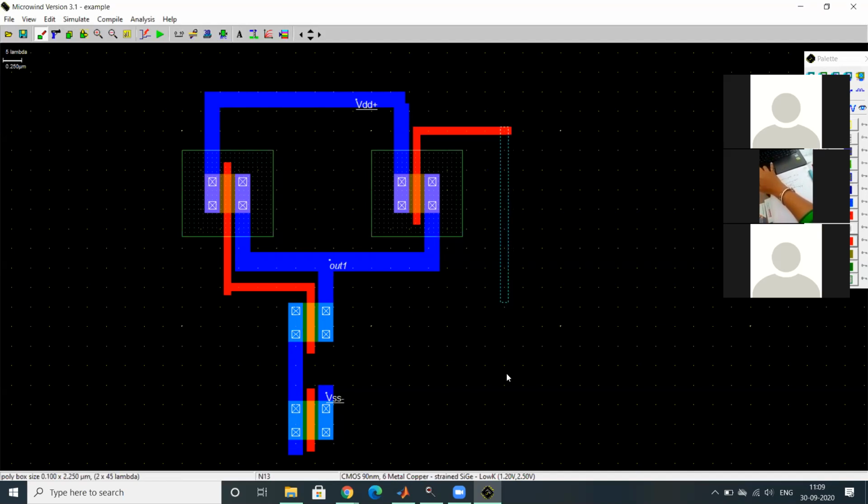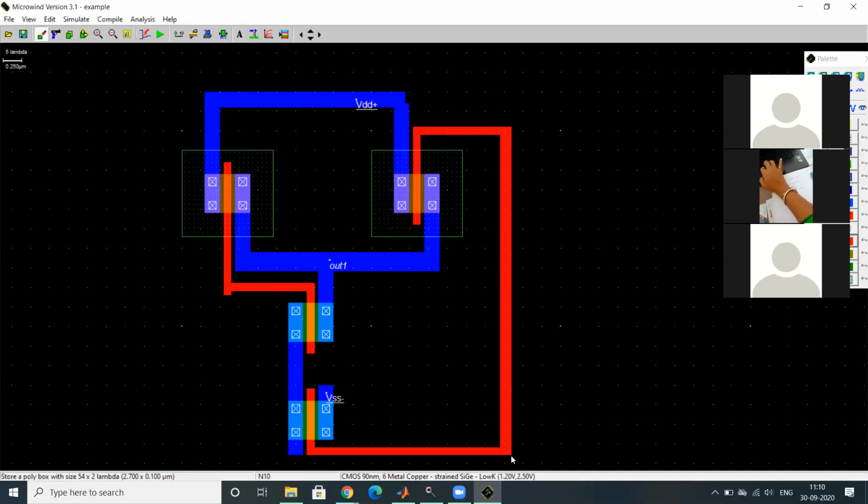So these are the extra polysilicon or metal lines which we are using, and this extra polysilicon can give you some unexpected output. Okay, so it is the designer's responsibility to take a very reasonable amount of extra metal or extra polysilicon. So this is just for practice, to see what type of connection we'll have and which type of NAND gate we are seeing. So all the things we have done properly. Now only the two leftmost things remain: providing clock A and clock B.